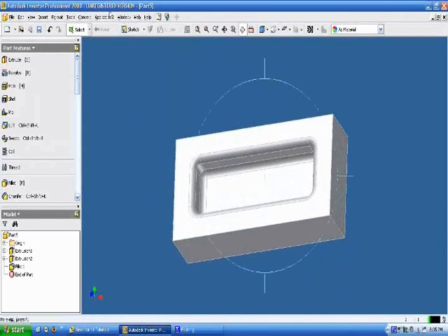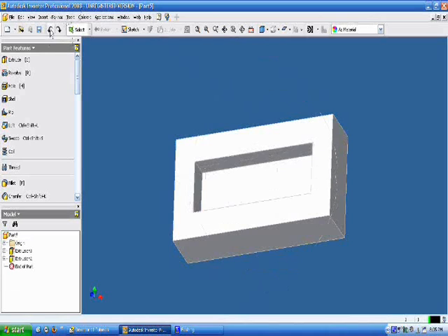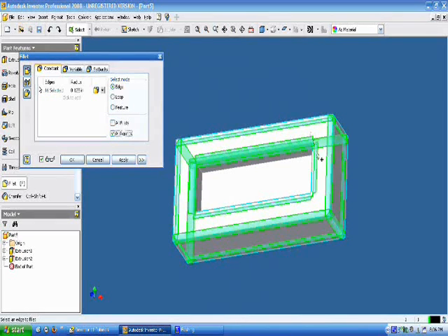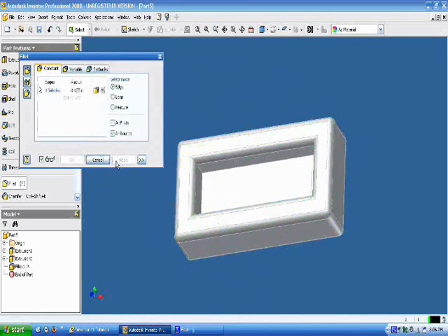Now if you would like to do all rounds, this is what you do. Let's go back to fillet. And these two checkboxes here, all rounds: Inventor finds all the rounds on this object and will automatically round them for you, so you don't have to select each one separately. Or same with all fillets. Let's click on that, and you see as it rounds all of the edges here, hit apply, and there you go. You've rounded all your edges except for the ones inside of the object.